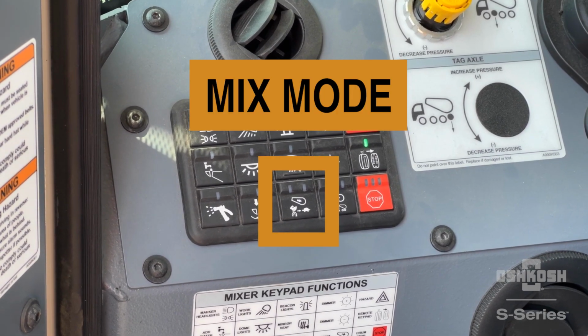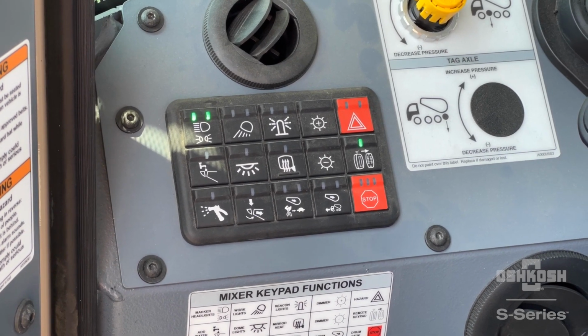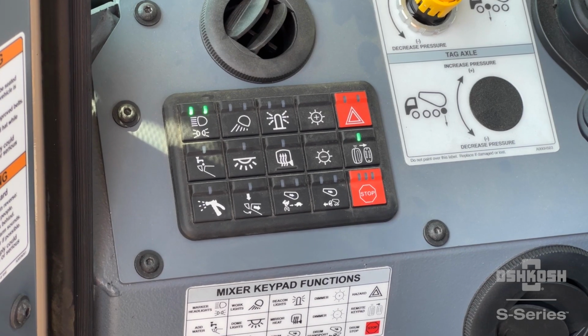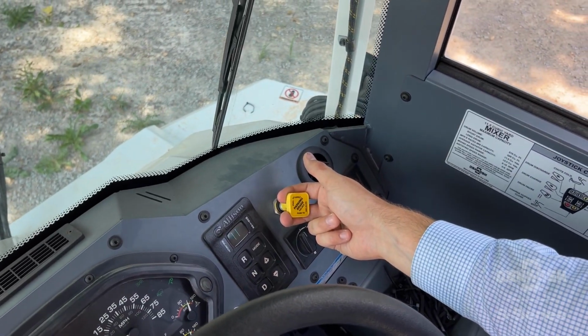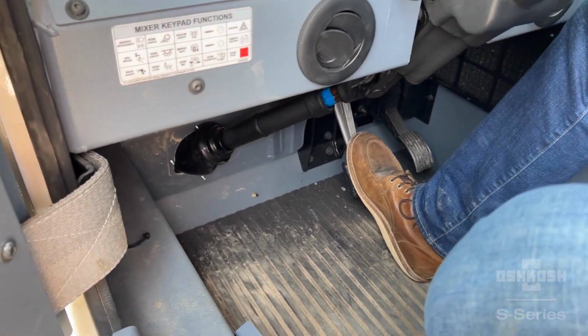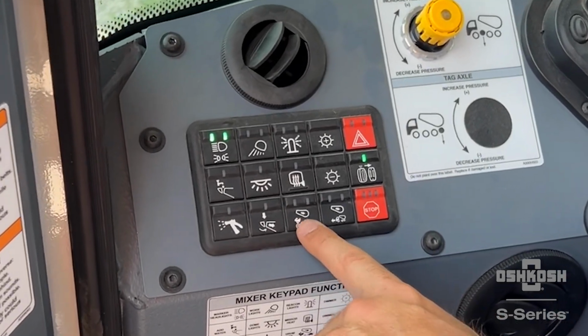Next, we'll talk about mix mode. The primary use case for mix mode is mixing the concrete. To enable mix mode, there are 3 interlocks that must be met before mix mode can be utilized. These interlocks are that the parking brake is set, the transmission is in neutral, and the service brake is not engaged. If these are met, simply press the mix mode button once to activate.